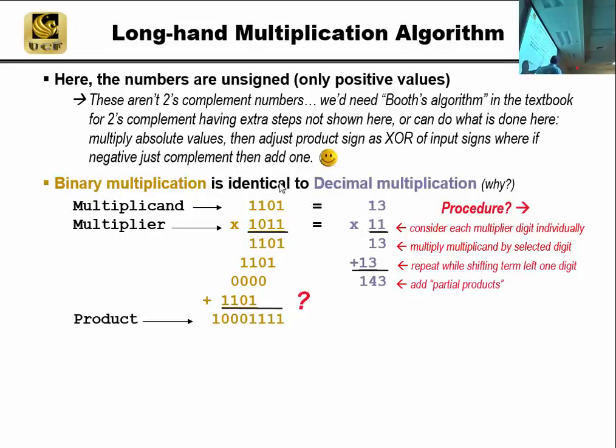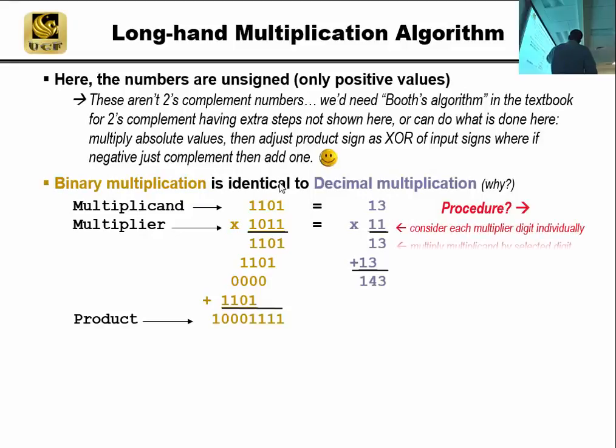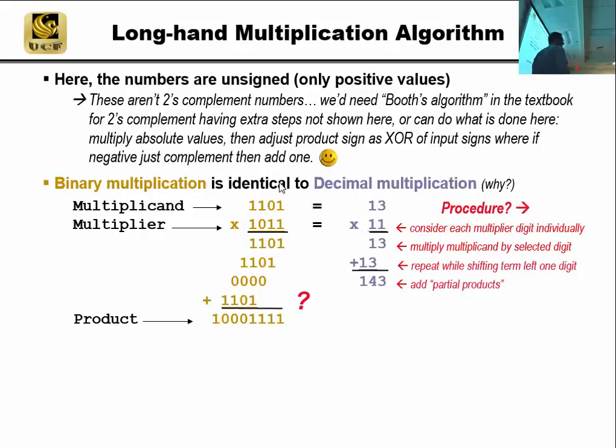So Miguel's pointing out that you get either what? You either get the multiplicand unchanged, or you get 0. Is there any other choice in the world? No. We're going to use that in our circuit. We can use a multiplexer because it's 2 choices. Now it's getting cool.